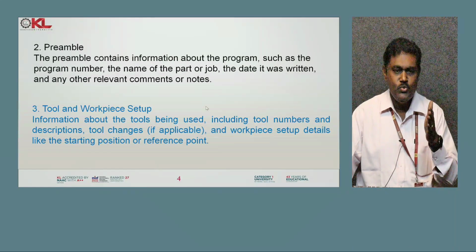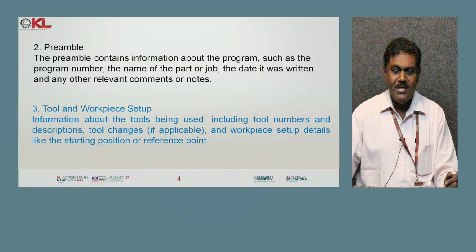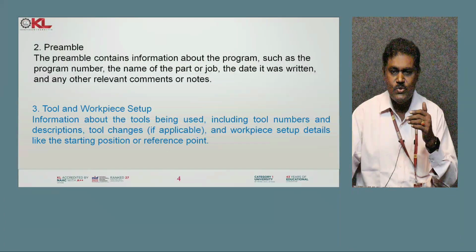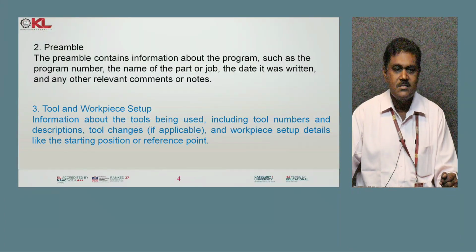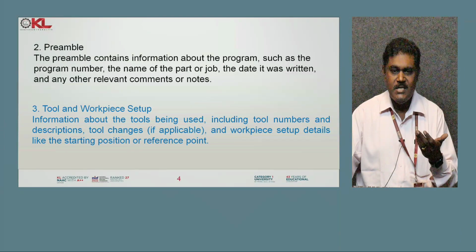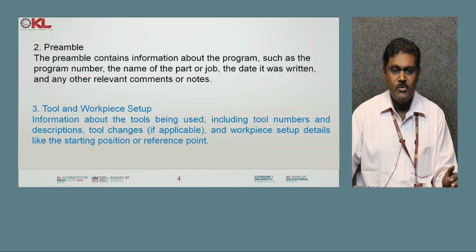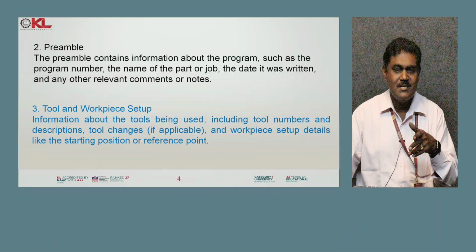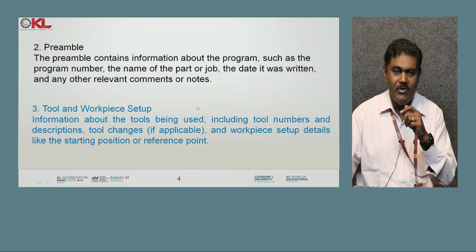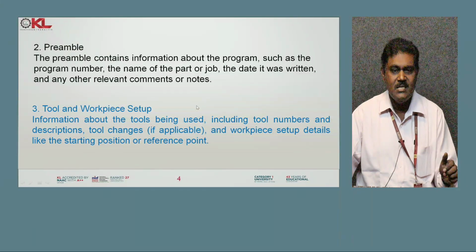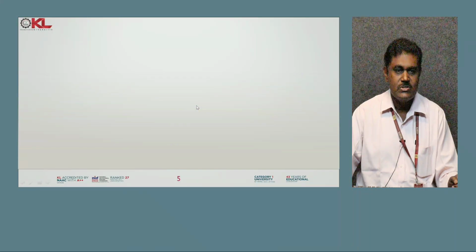The next is the tool and workpiece setup. Information about the tools being used, including the tool numbers and descriptions, tool changes if applicable, and workpiece setup details like the starting position and reference point. All these details we can write in the program. So whoever goes through the program can easily understand it with these notes.